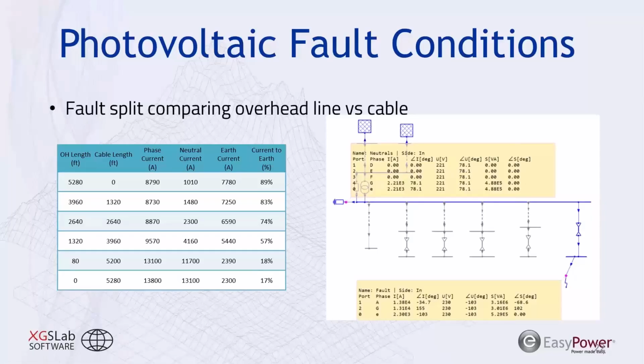And as we step a little bit farther down the chart, if we have a system that's just fully cable, just a 1 mile cable, we will see an increase in the amount of fault current that's available, based off of the fault current availability and the impedance, but we do see a rather drastic reduction in the amount of current that will go through the earth and produce our touch and step voltages. So your power system configuration is going to change the amount of current that goes through the earth, which produces your ground potential rise as well as your touch and step voltages.